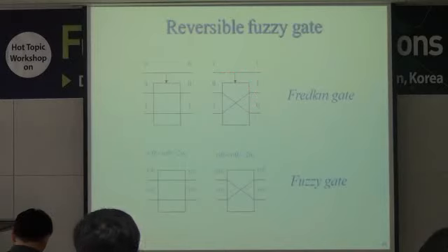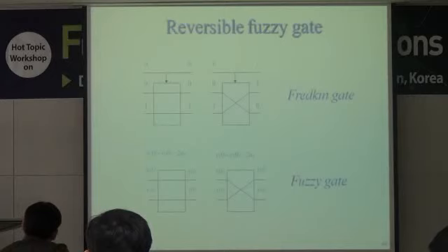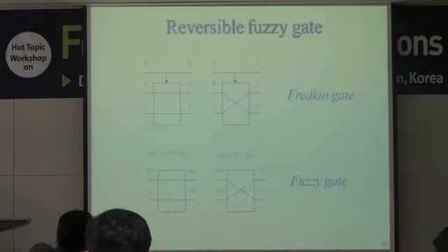We have found that a similar property can be obtained here by memristors. By initial settings we can bring the circuit to these two states and obtain again a gate which will not dissipate energy, for all the range from 0 to the threshold voltage.